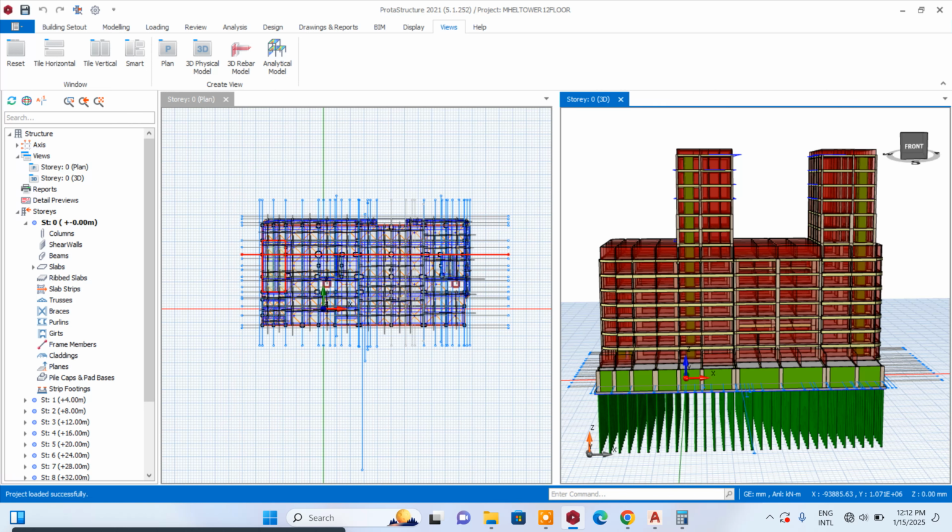And you can see that when you want to deal with raft on piles, the thickness of the slab is something very important that you must consider. In this case, sometimes you may even have a slab of about 1 meter, all depending on the load being transferred to the foundation. So you don't panic when you begin to have all of this, because at the end of the day, you will have your own result, and the result will show you those piles that cannot pass, maybe because they are closely packed together. So you also have to check the spacing of the piles, so that when the piles are installed, they do not crack. You avoid cracks, you avoid failure in the soil.